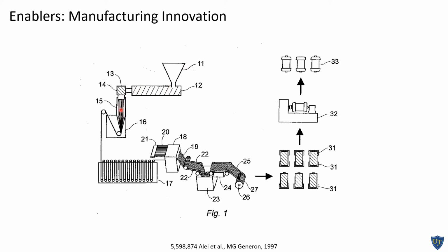These typically pass through a gap, a gas-filled gap, most commonly air, and then into a liquid bath in which the structure is set. After this, the liquid and solvents are removed, the membrane is dried, and then in this particular case, these fibers are woven into a fabric which is wrapped around a mandrel to form the module. The tube sheets are formed by dunking the module into a bucket essentially containing an epoxy resin that forms a tube sheet. The tube sheet is machined so that it has the right shape and fits into the module to produce the final object.